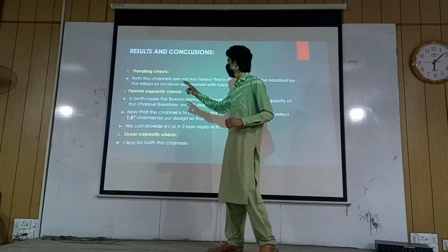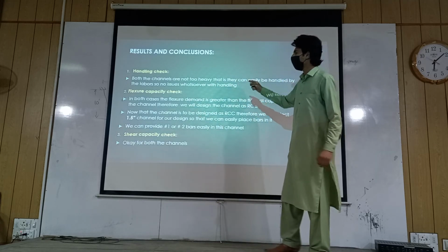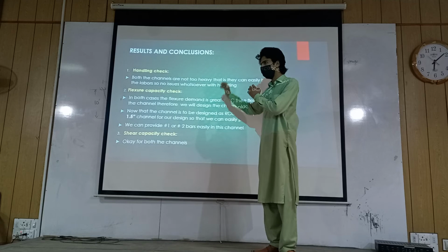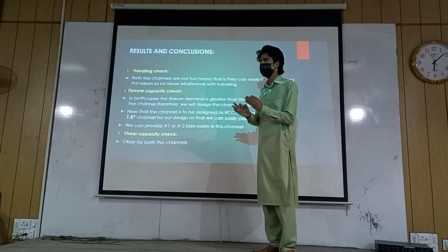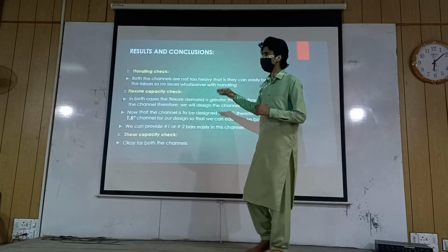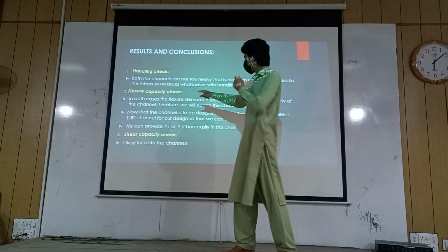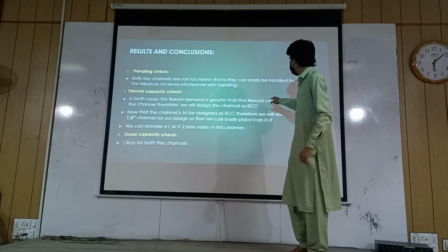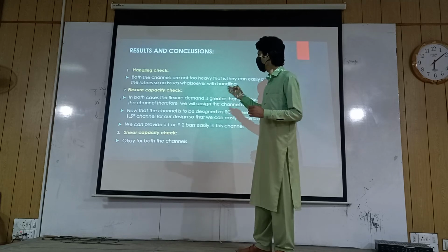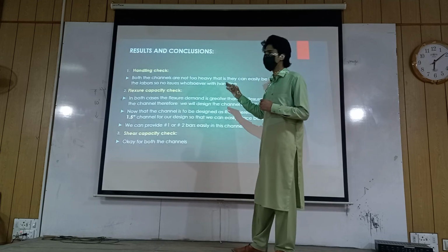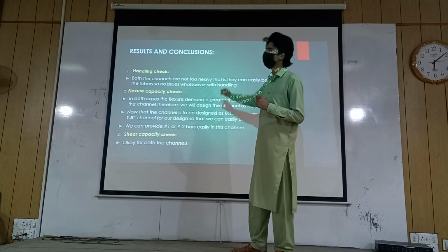First, handling check. Both channels are not too heavy. We found the total mass, and from that we concluded that both the 1.5 inch and 1 inch thick channels can be lifted easily. So this is okay. Then flexure capacity check. In both cases, flexure demand is greater than flexure capacity, so we concluded that we have to provide RCC, meaning we have to provide rebars in our design.